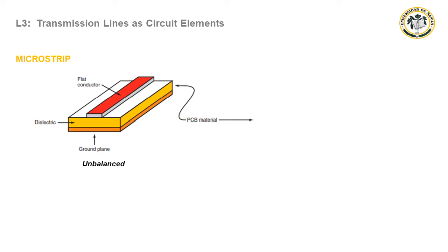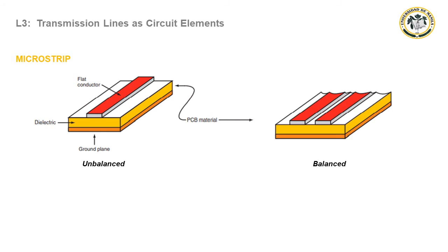So, special transmission lines constructed with copper patterns on a printed circuit board, called microstrip or strip line, can be used as tuned circuits, filters, phase shifters, reactive components, and impedance matching circuits at these high frequencies. A microstrip is a flat conductor separated by an insulating dielectric from a large conducting ground plane, as you can see in the figure.